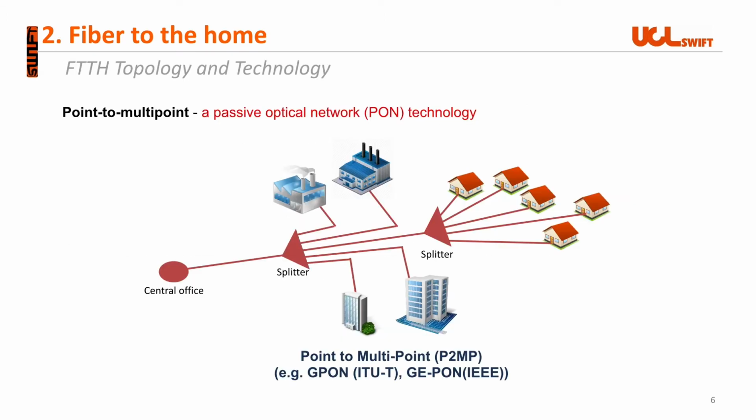A passive optical network (PON) is a point-to-multipoint FTTH network architecture in which unpowered optical splitters are used to enable a single optical fiber to serve up to 128 customers. A PON reduces the fiber and central office equipment required compared with point-to-point architecture. The downstream signal coming from the central office is broadcast to each customer premises sharing a fiber. Upstream signals are combined using a multiple access protocol, usually time division multiple access (TDMA).